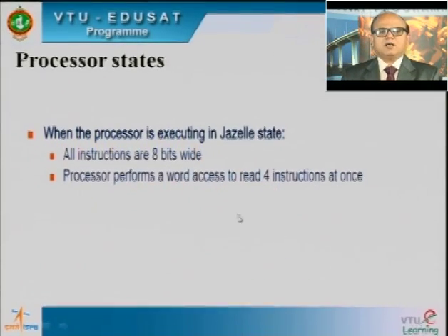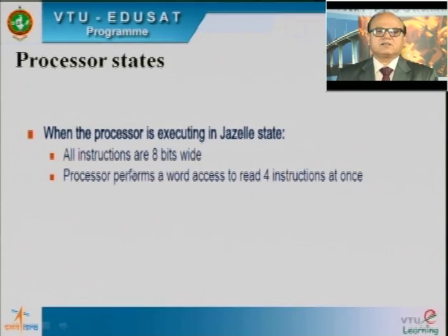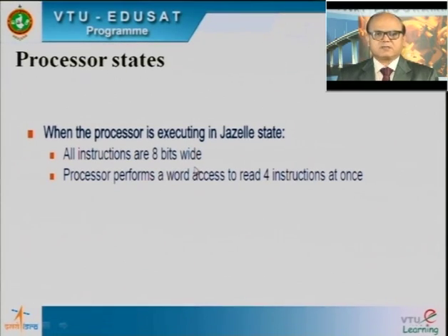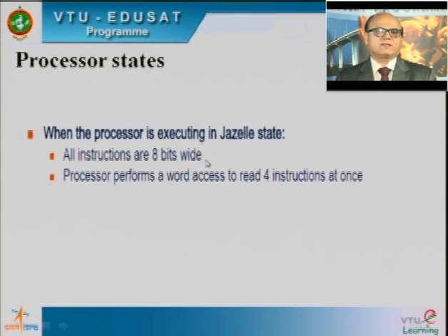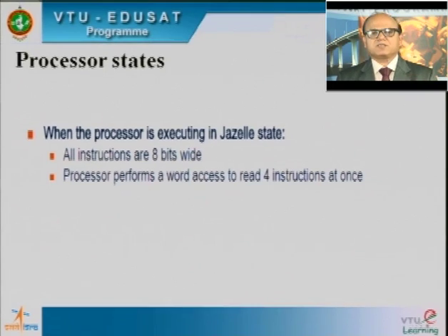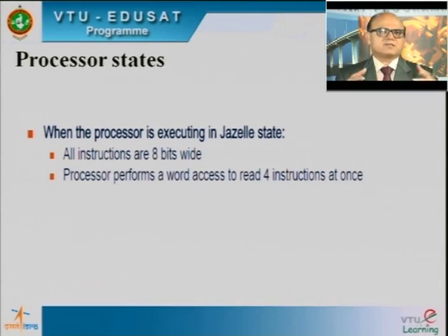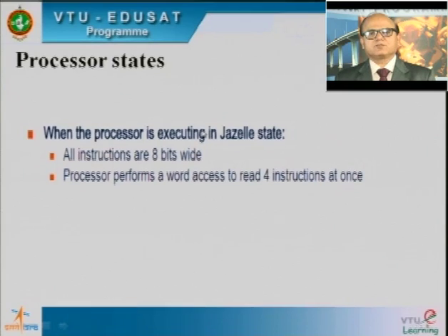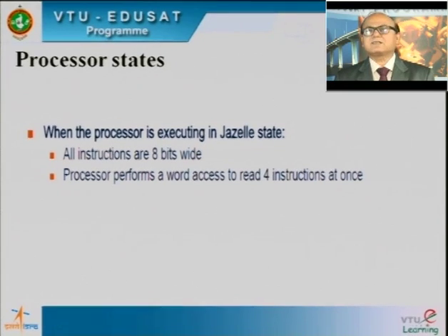In the Jazelle processor state, as we said, all instructions are 8 bits wide, so definitely I have no restriction. Any instruction of Jazelle state can sit in any byte. Whatever restrictions we had for 32-bit instructions and thumb instructions on where we can place those instructions in memory are completely relaxed when we come to the processor in Jazelle state.